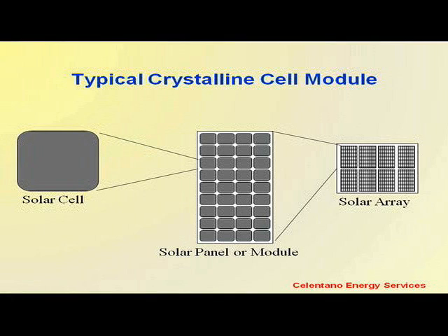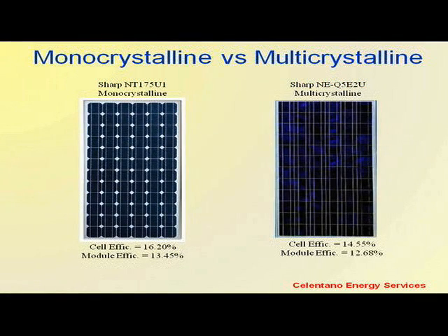Now, monocrystalline versus multicrystalline or polycrystalline. If you're out on the street and you see a panel, you can often tell, even from a distance, which is which. There are 2 things that give the technologies away. One is for a multicrystalline, and I hope this shows up, you often see this kind of random pattern on the surface where the light is being reflected in slightly different ways, and it's a bit of random bluish tint that you'll see here and there, because the crystals formed at random, and they look different.